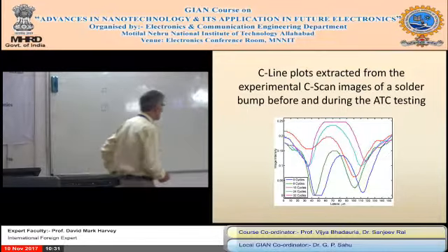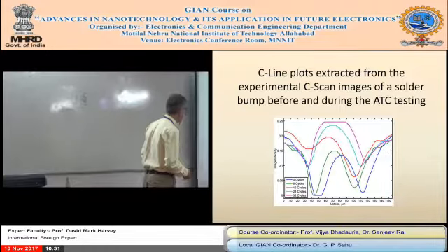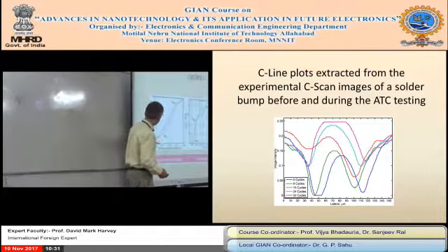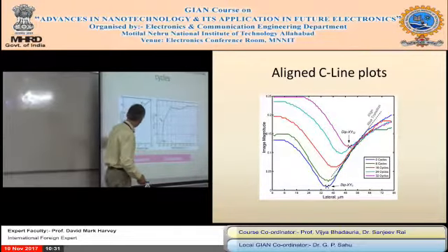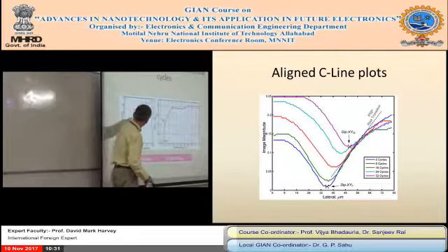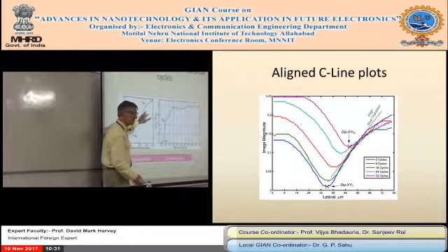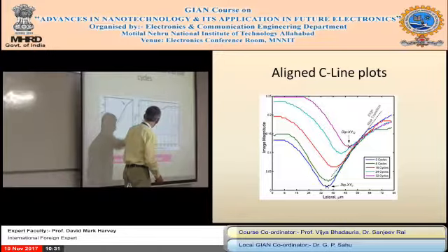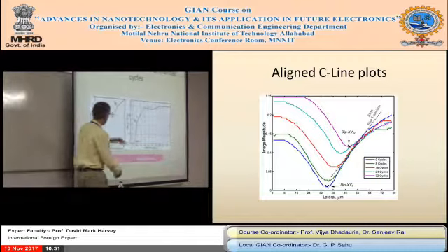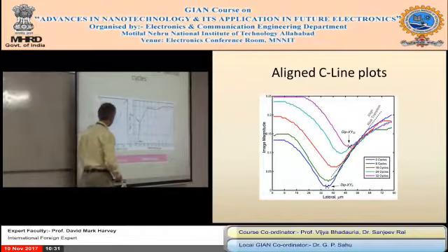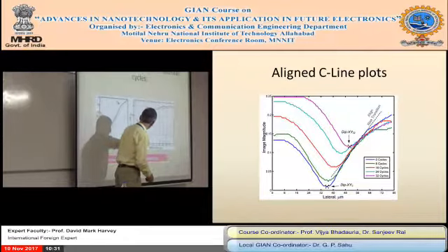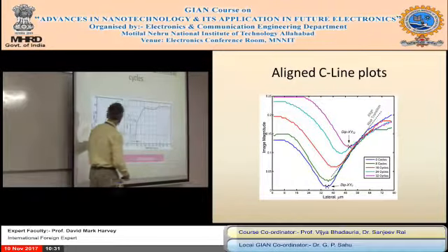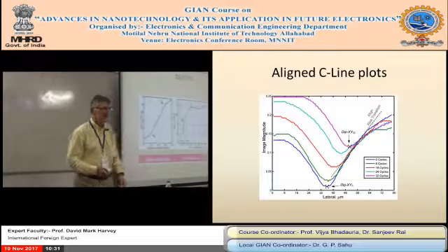So then, just as a sort of proof of concept, we got the experimental data, which is the thermal cycling. You can see we think it starts to crack just about there, around about 12 cycles, and by about 24, definitely by 32, this has gone up. There's a good chance it's broken. On this one, the simulated data, this is the width of the air gap. This is saying really that by the time the width of the air gap has gone up to there, this is corresponding to this, which shows that it should have broken.